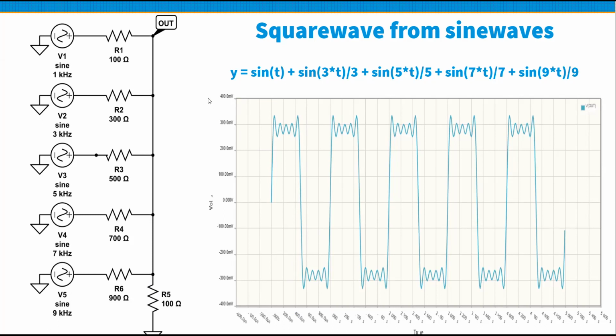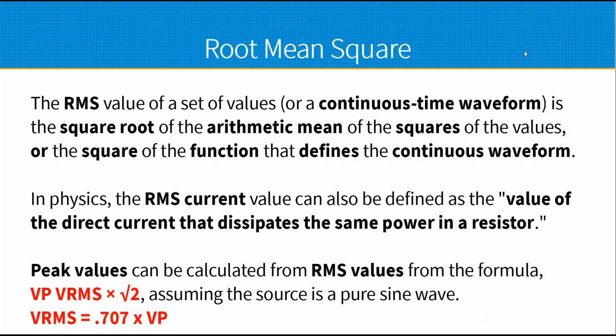So when you have an amplifier and you're getting clipping, where your sine wave is starting to get this flat top, it means it's generating all these harmonics, which is why it's a bad thing. Then your tweeter smells like the smoke ran out.